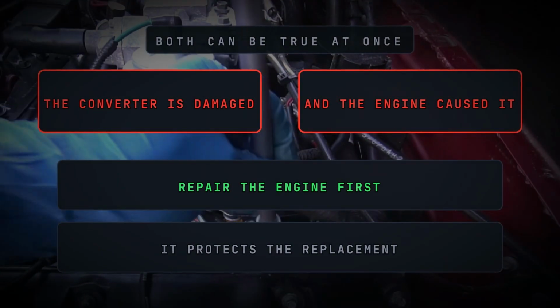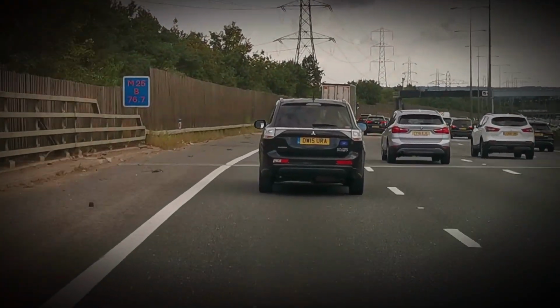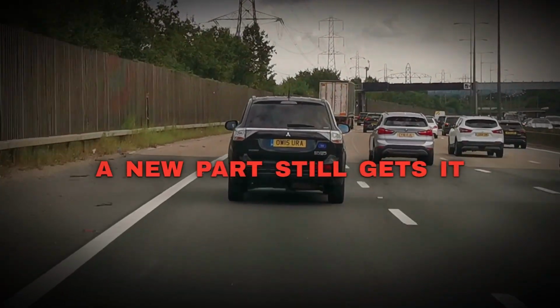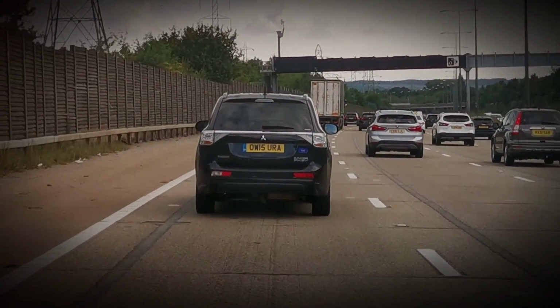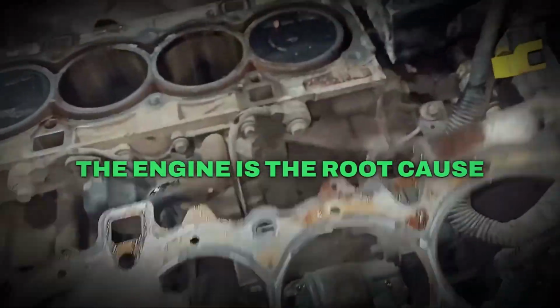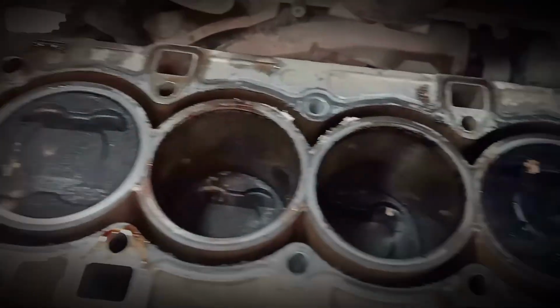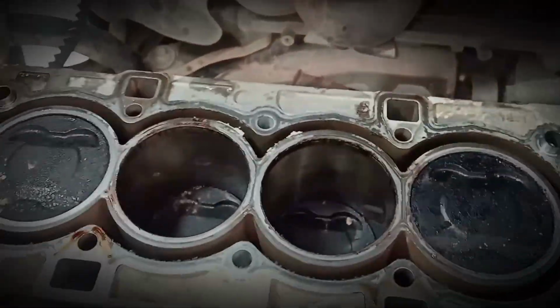Imagine installing a new converter on an engine that still misfires under acceleration. The new part may clear the code temporarily, but every hard acceleration sends the same damaging exhaust into it. The converter can be the failed part, while the engine remains the root cause. Once the engine condition is under control, inspect the components many people replace first: the oxygen sensors.